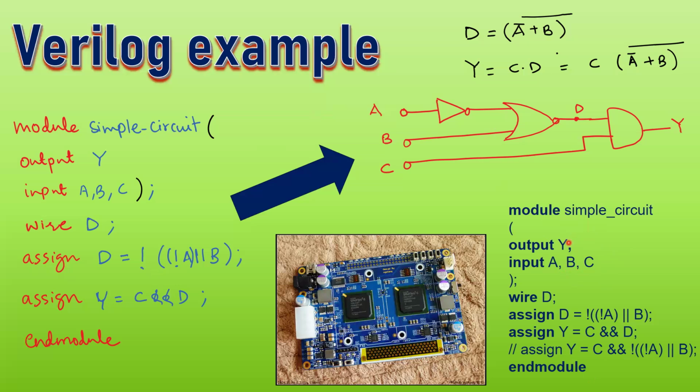Okay, so we'll understand the test bench in some other session. And once that is done, your simulation is performed, you verify the operation through the logic diagram, whether the circuit is performing as intended, and then you send that netlist to layout, and then accordingly your circuit can be sent to the foundry for manufacturing, and this is how you get the IC.